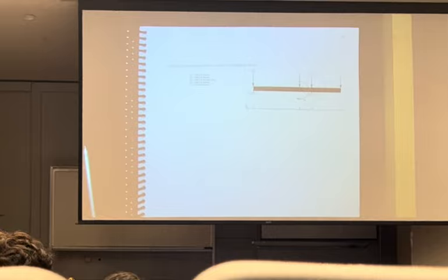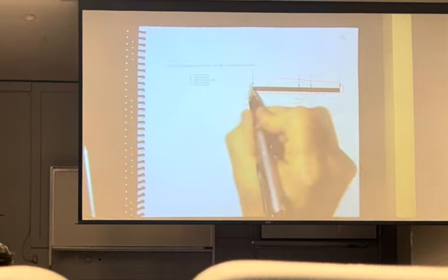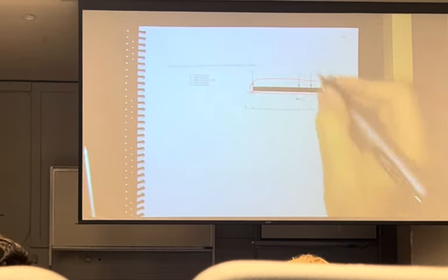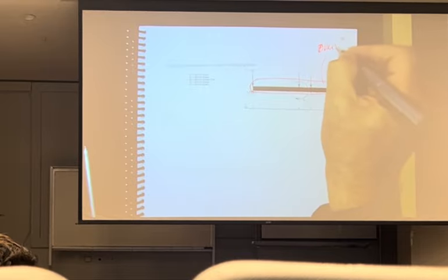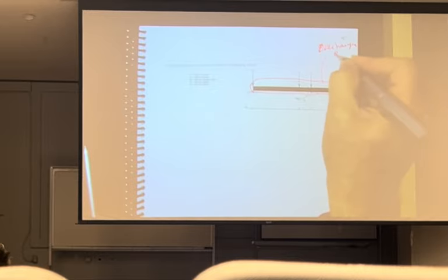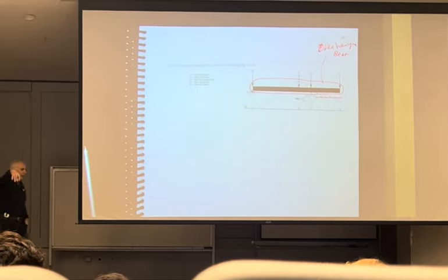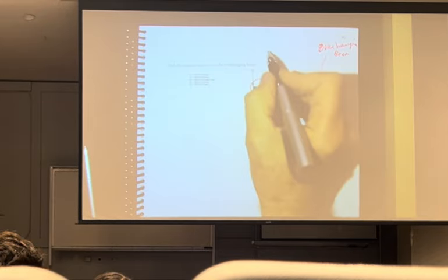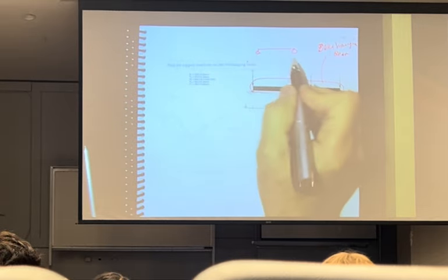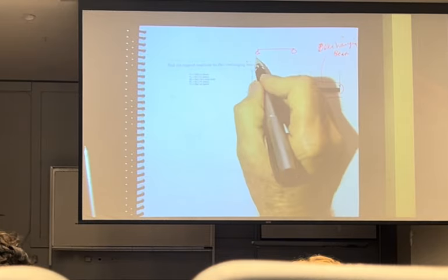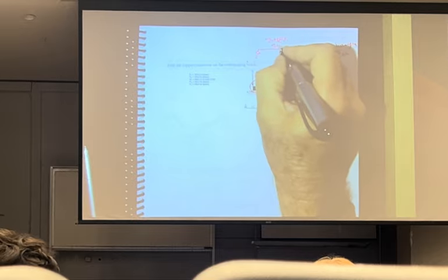Beam problems are the easiest because you cut here, cut there, cut around, and back. And by the way, this is known as an overhanging beam, because you've got this little piece that just sits, floating out in air, so to speak. This, where I have the pin and roller at one end and the other end, and it doesn't matter if the pin is on the left or the pin is on the right, is known as a simply supported beam.